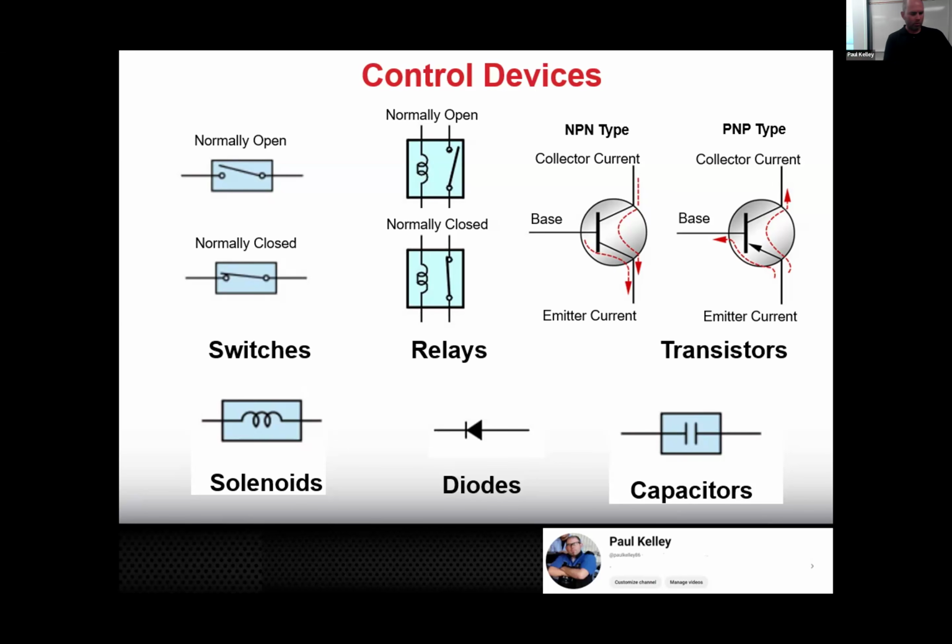And so what we'll do is we'll put a diode in there that will allow electrons to go down to the AC compressor clutch relay. But when we're engaging and disengaging it, it makes the voltage spike. The diode would prevent it from coming back in and spiking into the ECM. And some of those diodes are actually external. So that'd be like an AC compressor clutch diode. Okay, makes sense? Just a check valve. One way, yes. The other way, no.